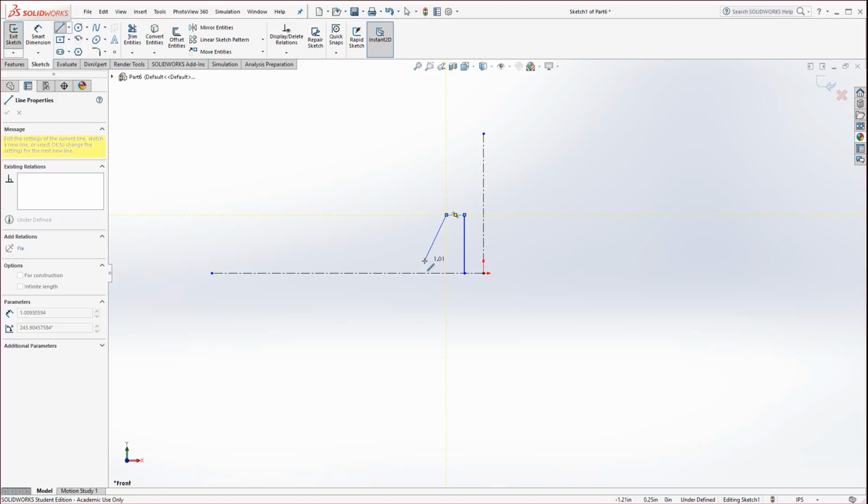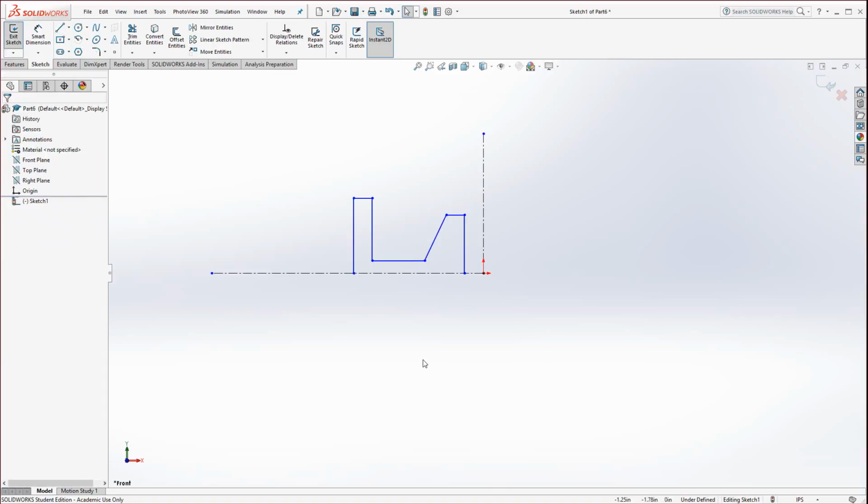And so just draw this out about 1 inch in length. Don't let it contact the horizontal center line. Just glide up above it like I have it. Click again. Now move your pointer to the left about 1 inch. Make sure it's horizontal. Click. Drop about 1.25 inch length line approximately. Click. A short 1/4 inch line is fine. Click, and now finally draw straight down vertically and connect to the horizontal center line. Go ahead and hit escape on the keyboard.